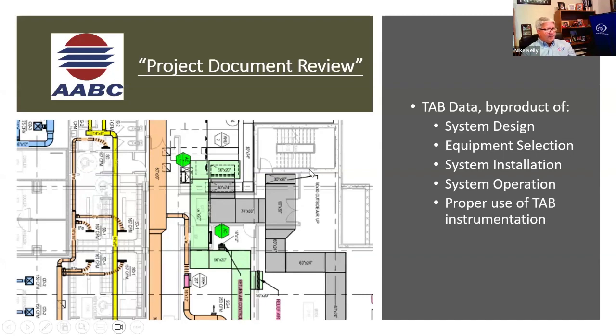It was something that got overlooked in design and installation. We also found it when we did an in-depth velocity test on the coil, but it also revealed that we had low airflow. But the way we were taking the velocities on the coils was not per their test method. So we ended up finding out that it was, in fact, a problem. But not to say our traverse was wrong. It just didn't incorporate the fact that where the unit was connected to the roof curb, there was airflow leakage, and it wasn't found until it was majorly investigated. We just thought the units were operating low and it missed the static on the design. But you've got to use that instrumentation properly and know how and when you're going to use it.